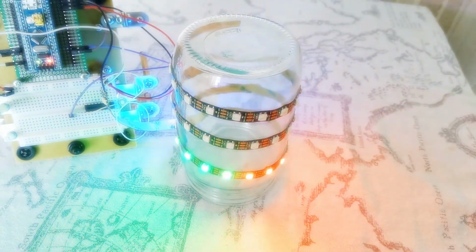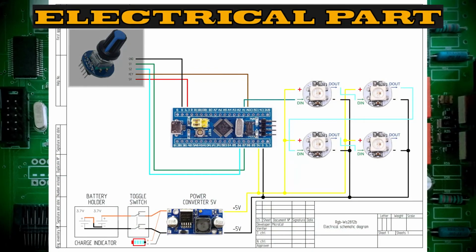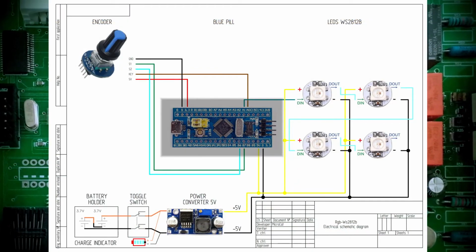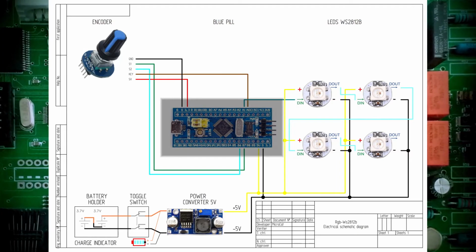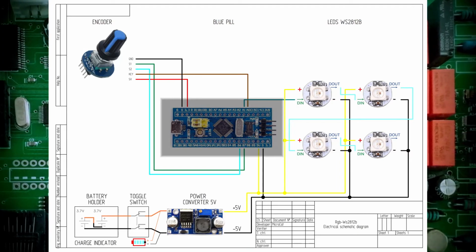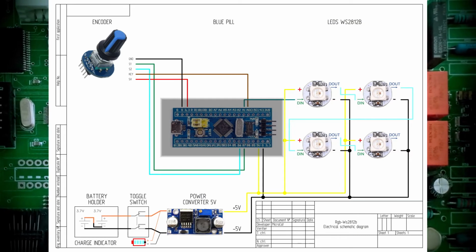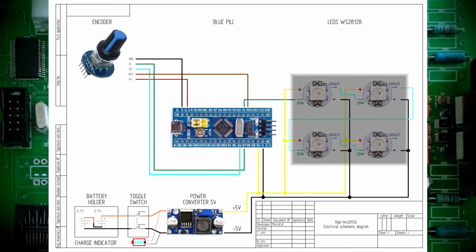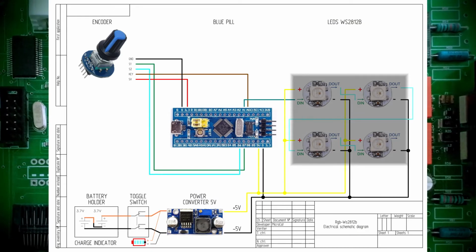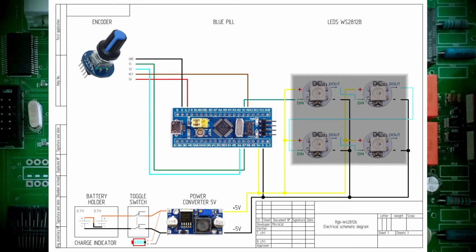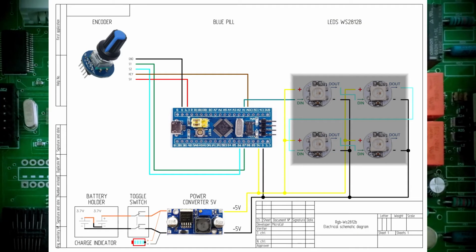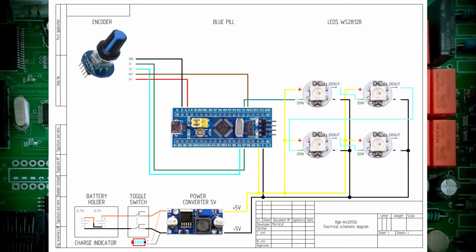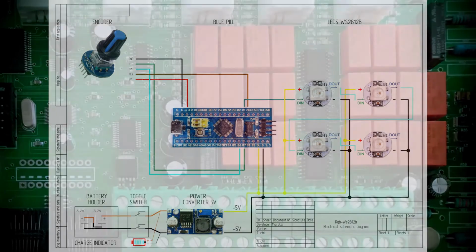Consider the electrical circuit. The master device for the formation of pauses is the encoder. The STM32 microcontroller analyzes the encoder counter and also outputs a 24-bit code. This code is for smart LED strip control. It is built on series connected WS2812B microcircuits.